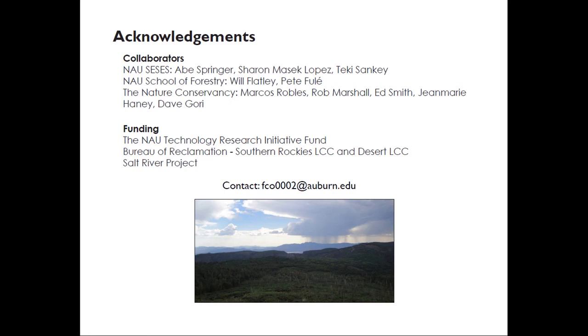From some of these historic watersheds where they did logging, you can look at the change in flood peak across different intensities of thinning, and you don't get a large effect until you're up to 60 or 70% basal area removal, and all of the restoration is below that. It is difficult to convince people of, though.